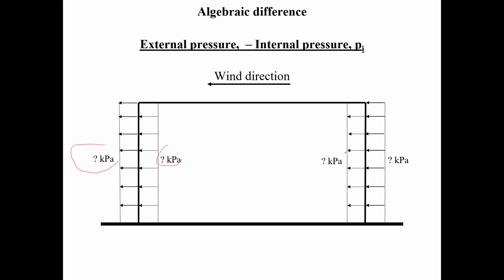Once you have that, you have your pressures. Then you multiply them by your tributary width, which is 0.6, and of course you multiply by whatever load factors, and you can get your WF for case number 3 and case number 4. So, hold on a second, let me clear the drawing.